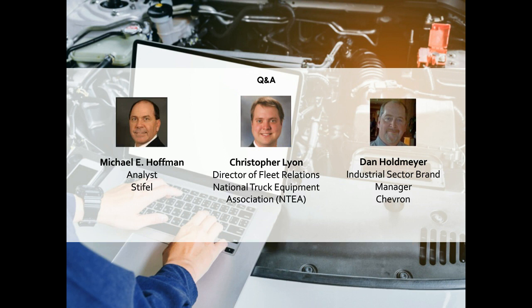So obviously fluids should be checked, but most important, an in-depth out-of-storage seasonal inspection. Most importantly, inspecting brakes, since things that have been sitting for several months tend to suffer from lack of use. So it's important to go over that inspection. We're putting employees in our vehicles, so we want to make sure we're providing them with the safest and most regulatory compliant tool for them to use.